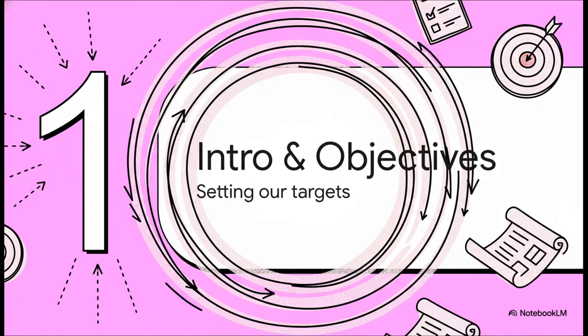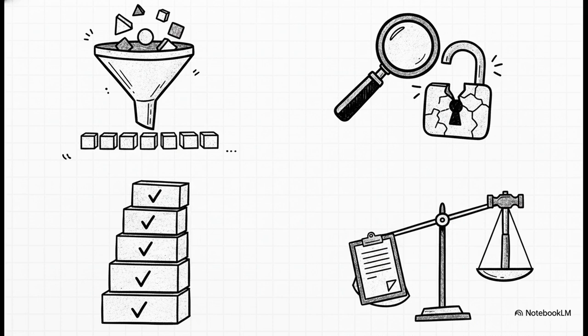Section 1. Introduction and Objectives. Let's set our targets. Our goals here are super focused on getting you away from just theory and into executing rock-solid workflows on the ground. By the end of our time together, you're going to understand the 6 to 8 week look-ahead window as a literal funnel of certainty. You'll master the basics of constraint analysis to systematically knock out roadblocks before they ever hit your crews. We're also going to show you how this generates a pure, constraint-free, workable backlog. Ultimately, we're fixing a massive industry headache, right? Matching what the master schedule says we absolutely should do with what the actual conditions dictate we can do.